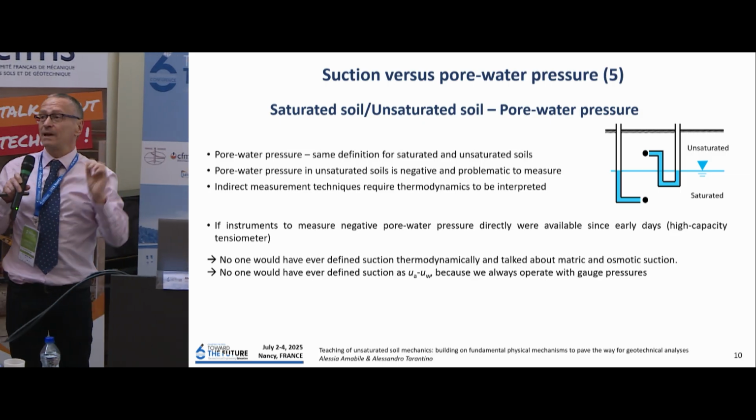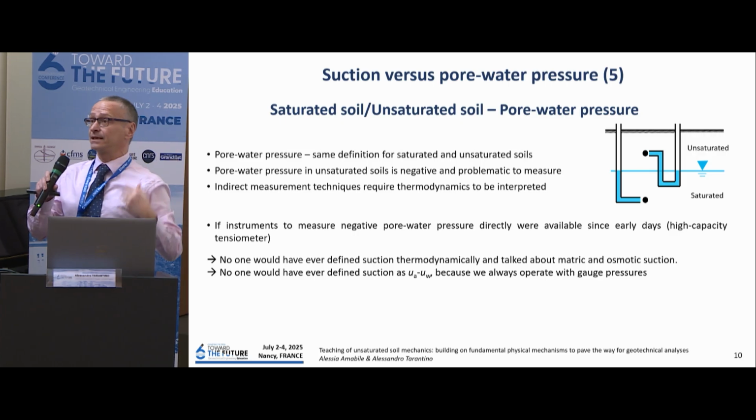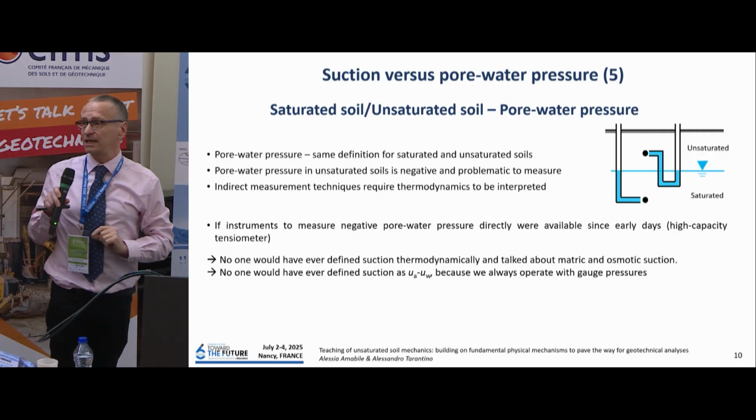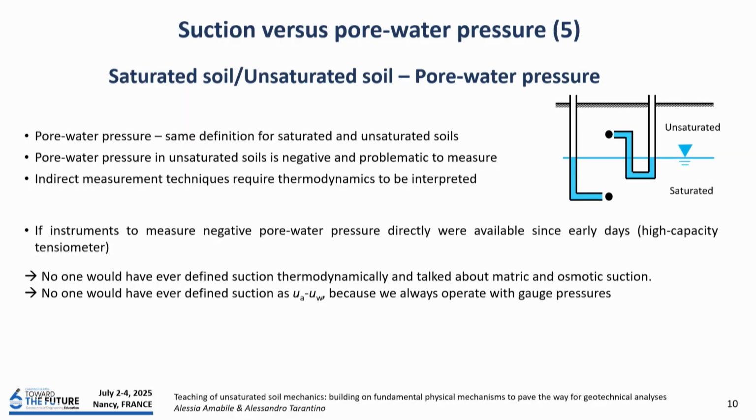If instruments to measure the negative pore water pressure were invented since the early days, you would have never defined the suction thermodynamically. You would have never talked about matric and osmotic. You would have not even talked about the difference between air and water pressure, because we are always dealing with gauge pressures.